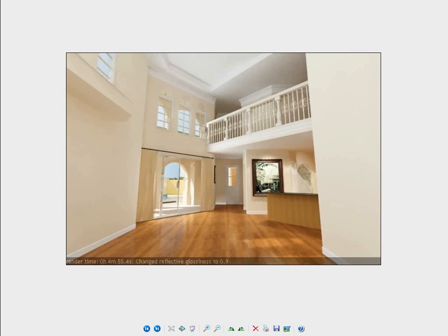The area that I'm probably going to have to focus on, and get most of these settings to improve, is the second floor ceiling, where light isn't as strong as it is in other parts of the scene. This is my weak link, so to speak, and if I can remove the noise here, I won't have to worry about noise anywhere else. So I could just do a test render here of this area, but since I also need to worry about the detail of my entire image, especially in the crown molding area, I'm going to render just the entire scene.